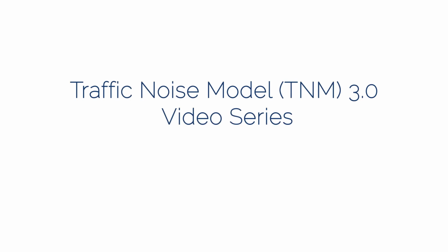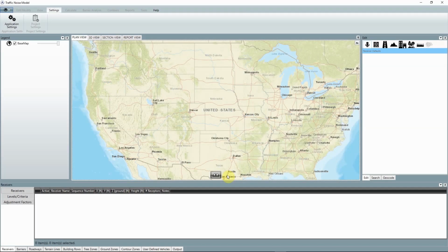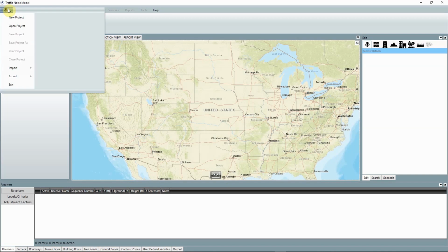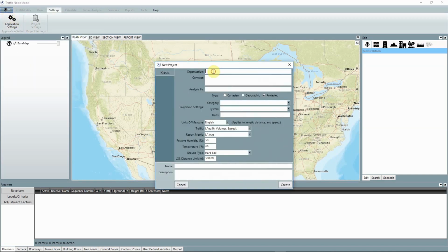This video will describe how to create a new project in T&M 3.0. First, open T&M 3.0. Click on the File tab and select New Project. Fill in any appropriate information for the organization, contract, and analysis by fields.